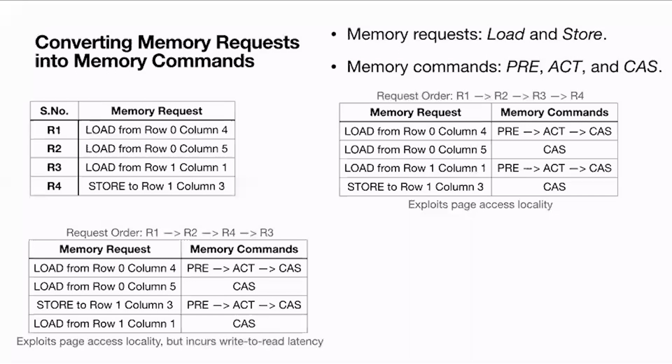This is because the DRAM DIMM is servicing both read and write operations, and there is some circuitry which is used for both operations. If you are performing a write operation and then want to perform a read operation, you have to wait for some amount of time so that this output circuitry settles and is ready to process the read request. So we have to wait for this store to load, or write to read, latency. WTR, we typically call it.